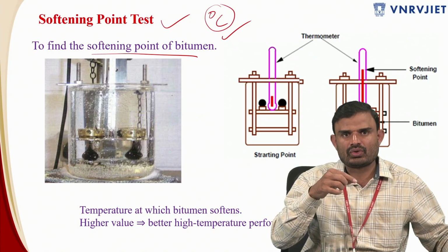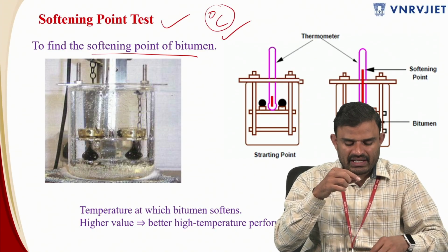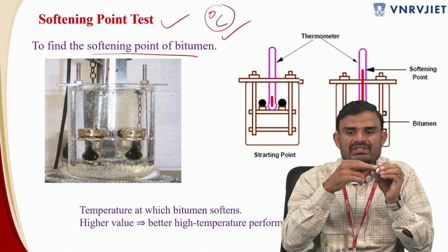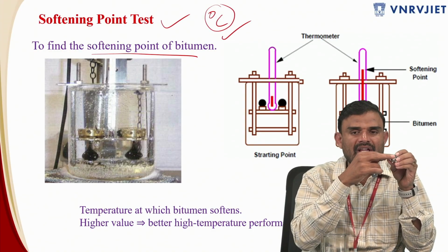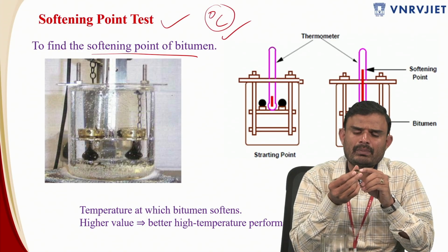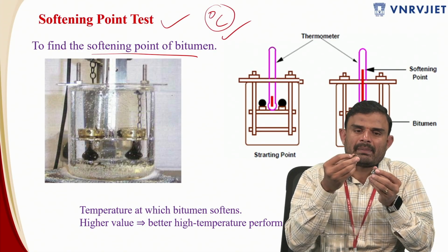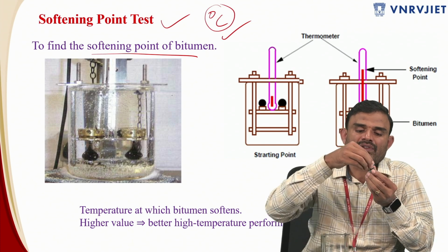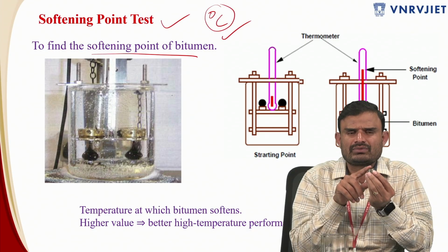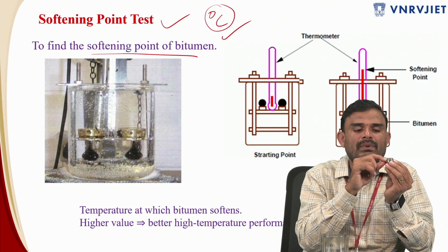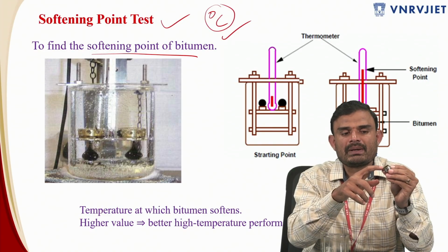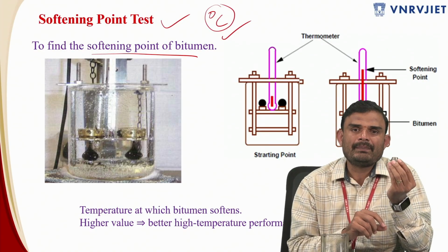You bring this sample like this. This is our original ring, and there is another ring, which is a supporting ring. You'll have a groove on one side of this supporting ring, and a groove on one side of this original brass ring. This groove will be upside, and this groove also will be upside. You just insert the top ring inside the bottom ring. You get 3 steps: 1 step, 2 step, 3 step. This is how you fix your brass ring.